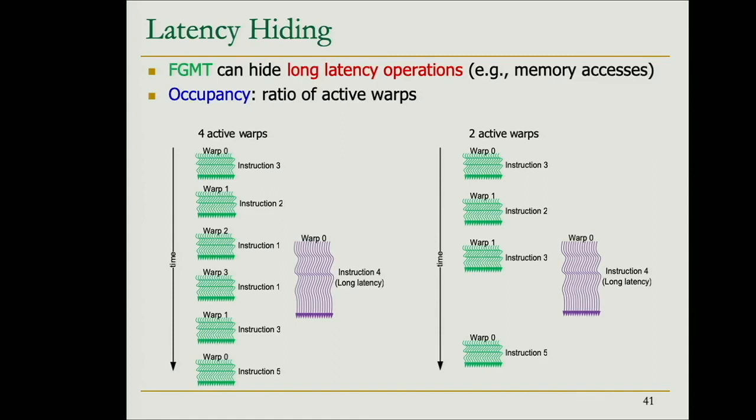No, actually not, because the instruction cache is not a problem, because all these warps are running the same program. So if you review the slides that I showed you the other day, one of the things that determine the maximum number of threads in a generic fine-grained multi-thread architecture, or the maximum number of warps in the GPU, is the number of program counters that you have.